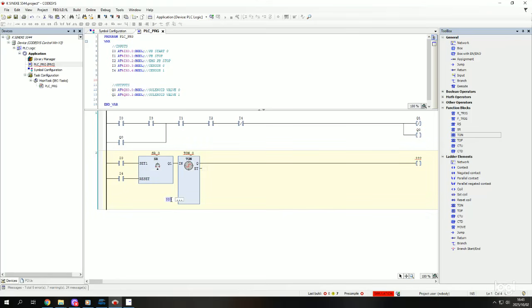Then here is where we program our time: capital letter T, hash, the seconds of the delay. You want the delay to be 5 seconds, 10 seconds? So 5 seconds. The 5 is 5 seconds, and then I write a small letter s to represent seconds. So it's T#5s. So the time delay is 5 seconds.